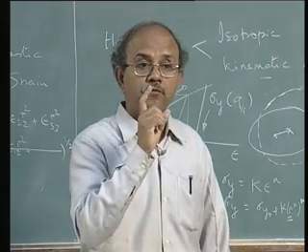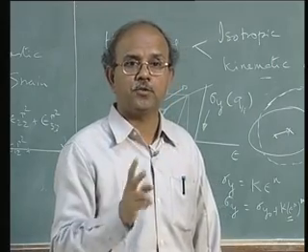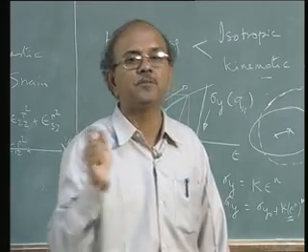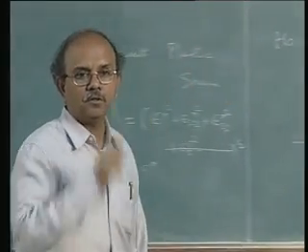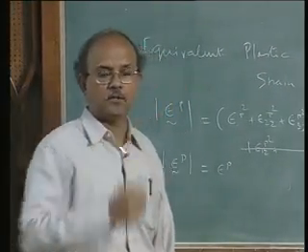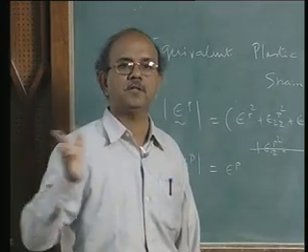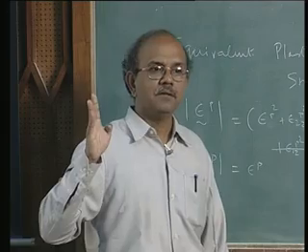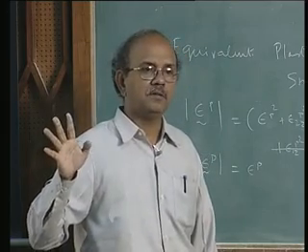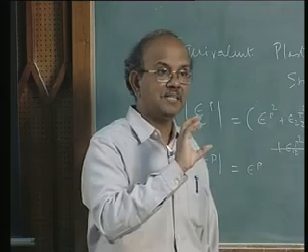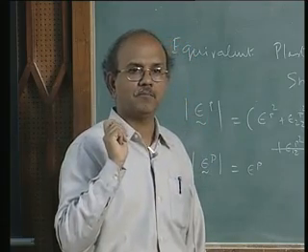So, when I look at the elastoplastic situation, we are not in the incompressible regime, we are in a nearly incompressible regime. There are some issues in incompressibility which is different from compressibility. When it is totally incompressible, the algorithms which I have to use later will be slightly different from nearly incompressible materials.